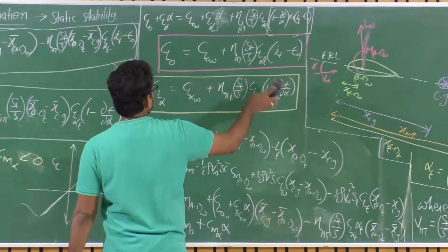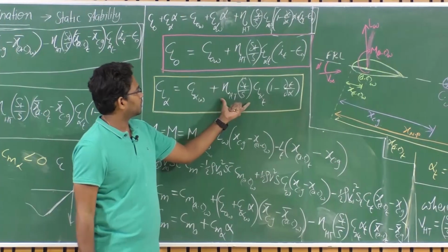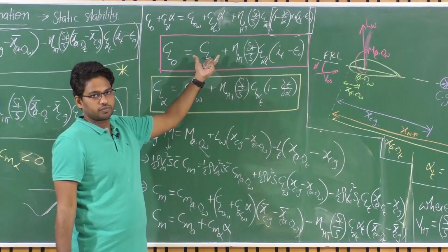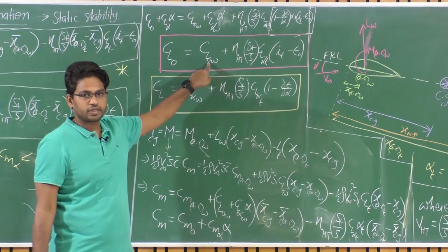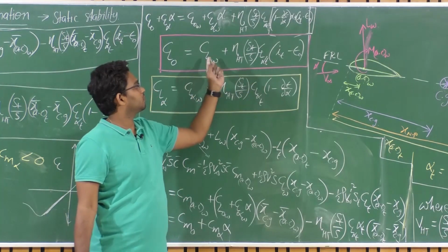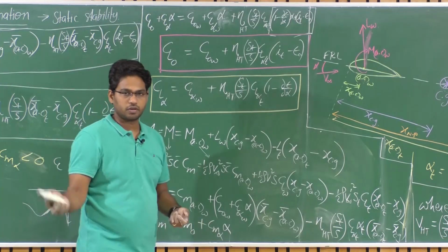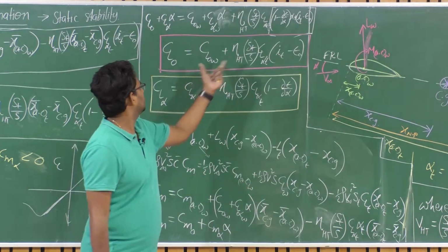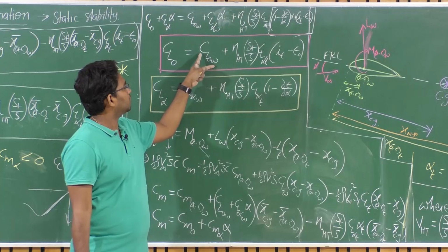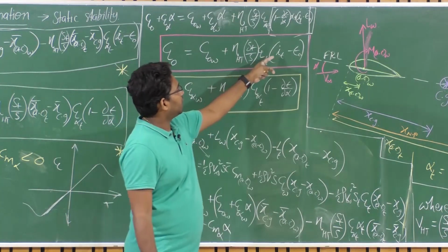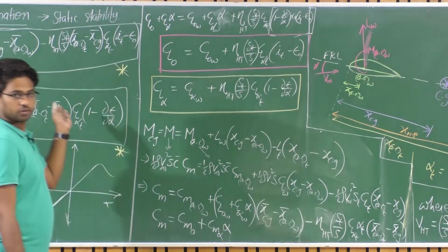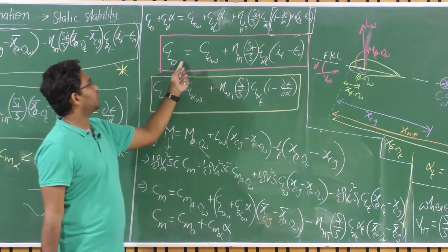So I'm erasing this particular part, right? And see if you can notice this particular portion, CL naught plus CL alpha. This CL naught of the entire aircraft for this wing and tail combination is positive if it is a cambered airfoil. If it is a symmetric airfoil, this is 0, right? And if there is no i_t, this term most likely vanishes without any epsilon naught, assuming epsilon naught is very small. So the CL of the entire aircraft is 0 in that case, right? If it is a cambered airfoil, that CL naught is positive, right? And if you have i_t negative, this term contributes negative, because you want i_t to be negative for Cm naught to be positive. Am I correct or not?